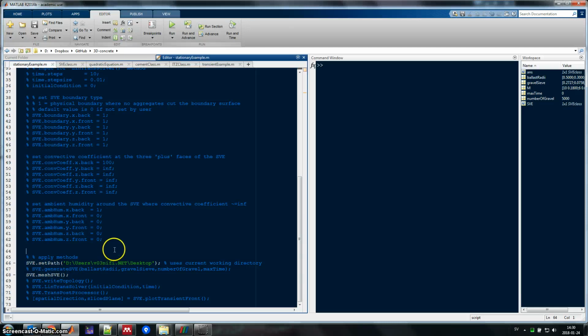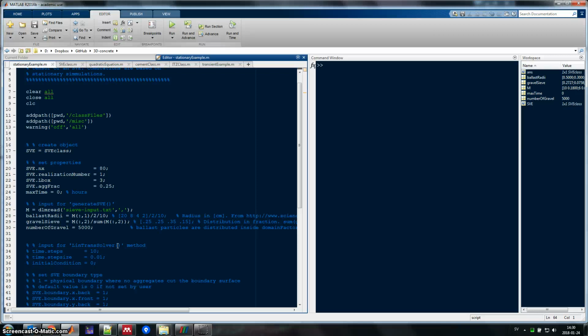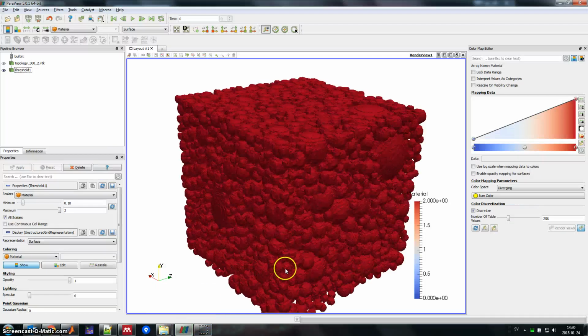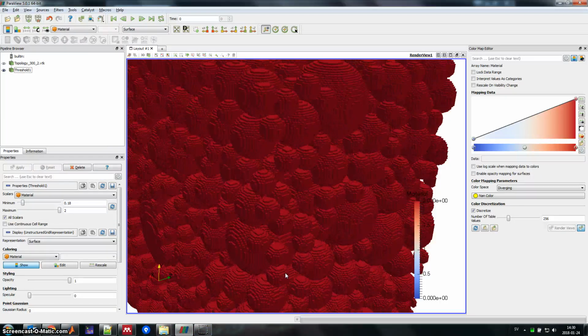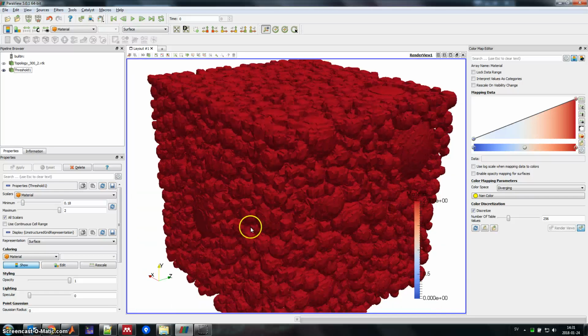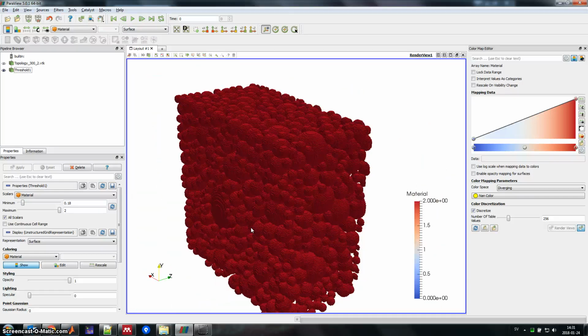So the only object property of these properties that you want to set now is this value here. So now we set nx to 80. nx is the number of elements along each length. So if we zoom in, this has a very high resolution. So the number of cubes or voxels in each direction is nx. So you will have in total the value of nx to the power of 3 number of elements. So nx to the power of 3, that's the amount of elements that you will have. And this could be any value really.